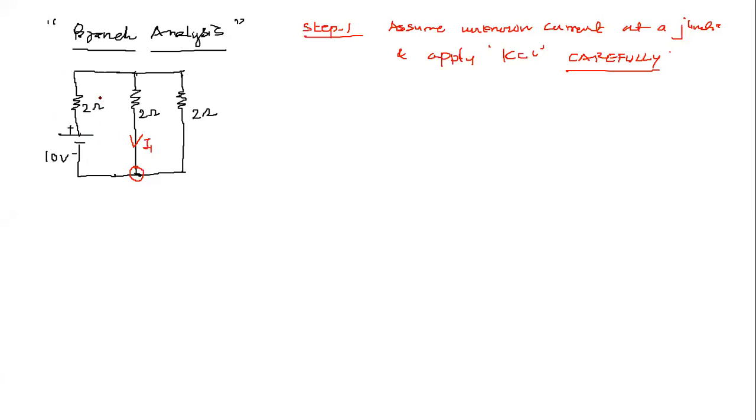In some complex problems which we are going to solve later, you will find that the source is taking current, and we'll see that also. But right now, this 10 volt source is supplying current, so it is wise to choose this way. Otherwise, we'll get a negative answer. In the last lecture we discussed what happens if I take a reverse direction of a current.